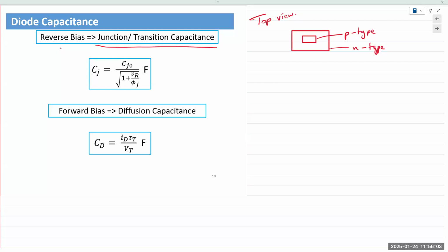And so it creates a capacitance that can vary or increase as a result of the applied voltage. That is known as the junction capacitance, and that capacitance is a function of the voltage. So we can model a diode as a voltage controlled capacitor. And there are special purpose diodes known as varactor diodes, where we use the property of the diode capacitance.